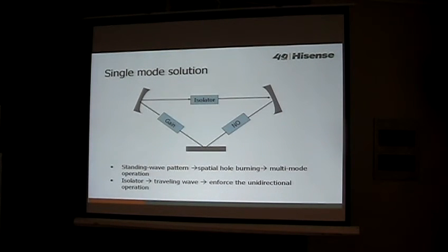Another solution is to use single-mode operation. Obviously, once you only have one mode, the laser operation will become much more stable. We have said many times that if we add filters into the optical cavity, we get stable single-mode operation. But here I would like to point out another thing. If we just filter out all the wavelengths and leave only one wavelength, we might still not get single-mode operation.